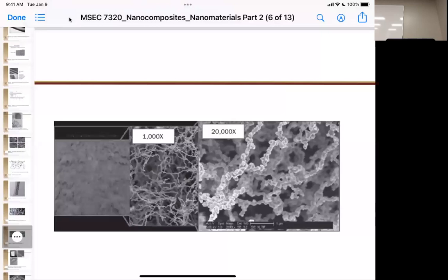You have to be careful about sintering processes because nanomaterials have lower melting points than their bulk property. So if you try to say, oh, I have the structure, I'm just going to melt the polymer off at 200 degrees C, no, that might be the melting point of your nanocrystals, and they'll just kind of all fuse together. But we can see that, and so that's what these two images are. But you can see that it's dispersed in a matrix. Okay, does that answer the question?